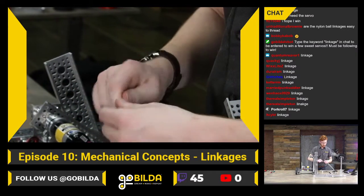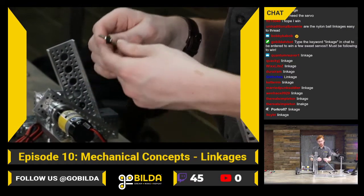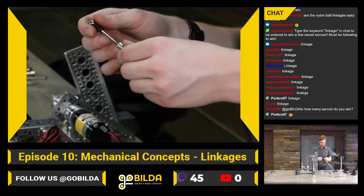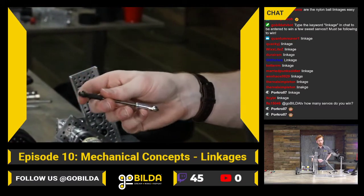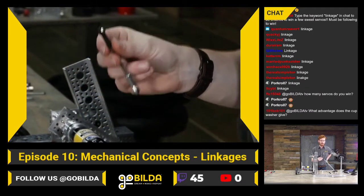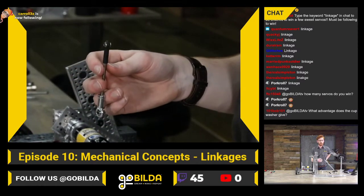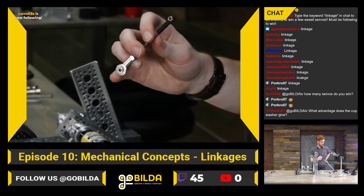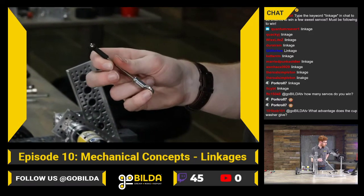I think that works out really pretty well, and you get a basically already installed system. I would say for almost every application in FTC where you're using a servo to drive a mechanism, nylon is going to do it for you. It's going to cost about half as much as a steel ball link will, and it works really pretty well.